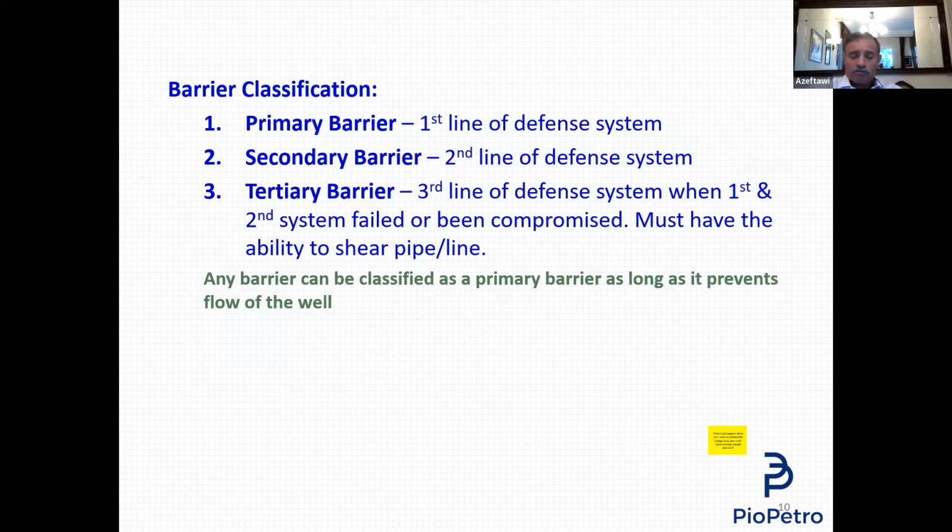The shear seal is also not necessarily in every rig up you have. So your tertiary barrier might be the Christmas tree itself, where you can close the valve to seal. Closing the valve, yes, you can use the master valve. Normally, it cuts the slickline, because the slickline is a stainless steel wire, of one certain diameter. So the master valve can cut it. Some master valves are designed to cut this slickline, not all of them. It has to be designed for it.